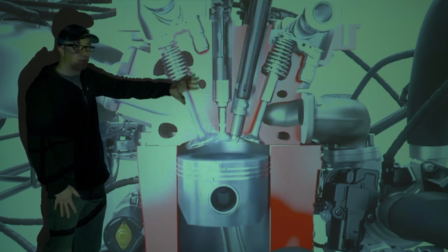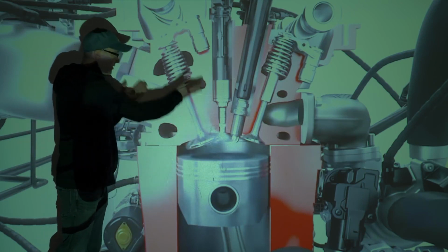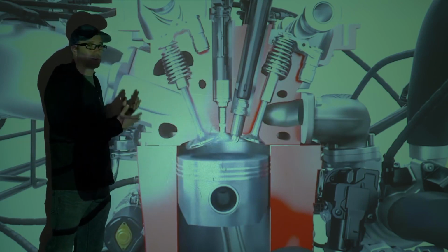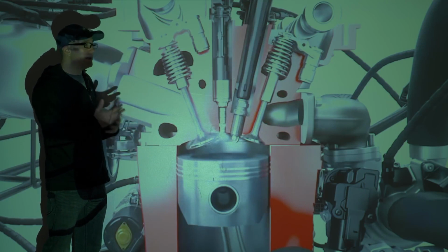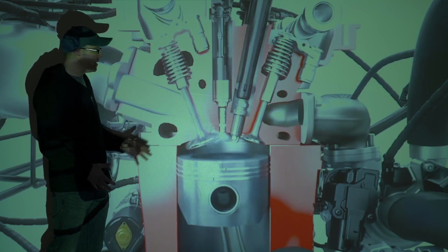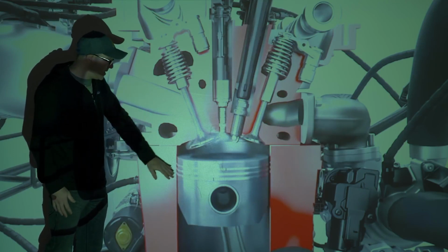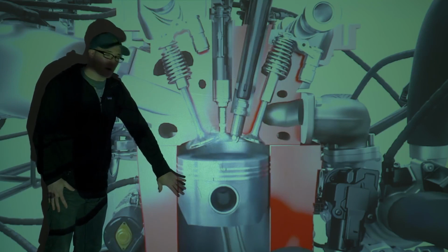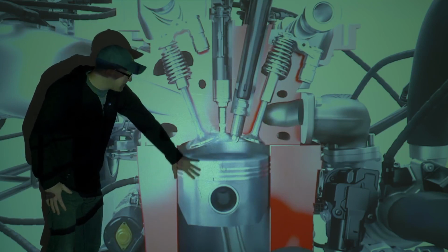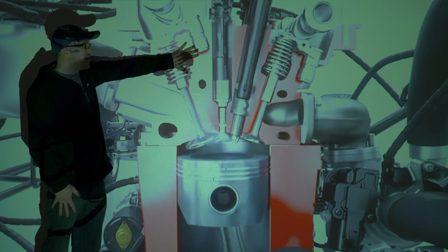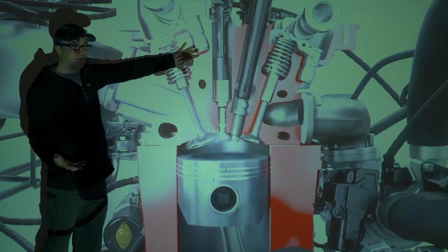This happens with direct and port injection because you have pressure that comes up. It's just natural for some cars, and some cars it's worse. It just depends on what type of motor you have. No motor is the same. But what both cars do as a strategy is, as that pressure moves up, they need a way to ventilate it out, and that's what you call a PCV system.